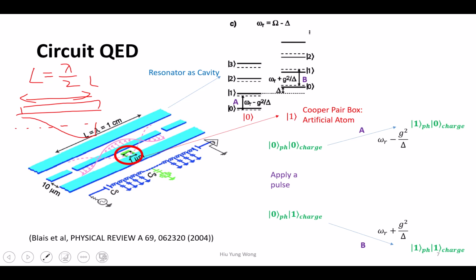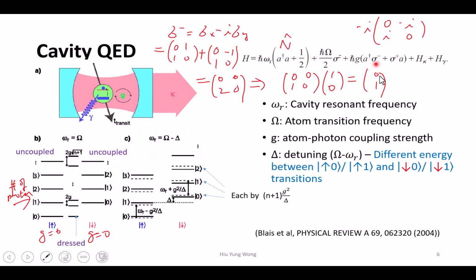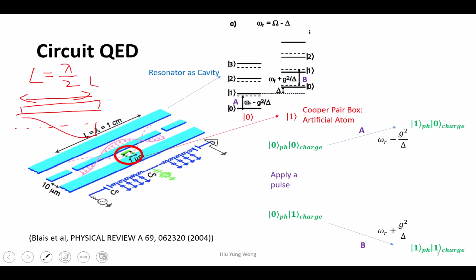That happened because of the system, the coupling. Because now the system is not purely these two terms. The resonance frequency of this resonator without the transmon is, let's say, 5 gigahertz. Now I put a transmon there. In principle, you should expect that the whole system resonant frequency will change.